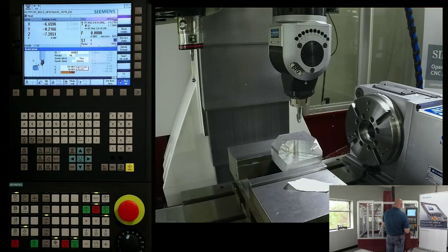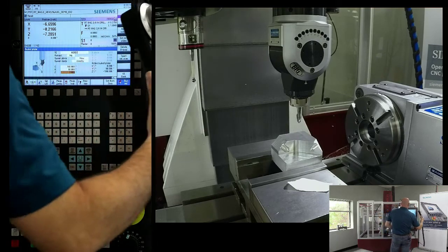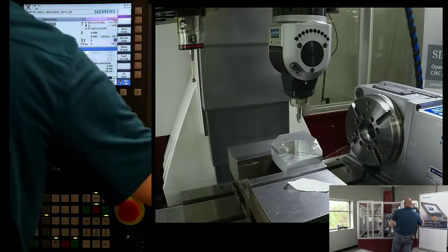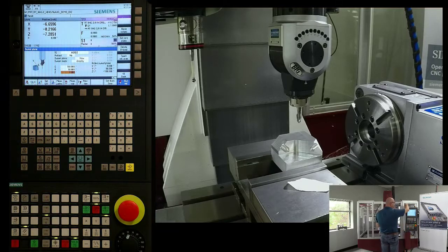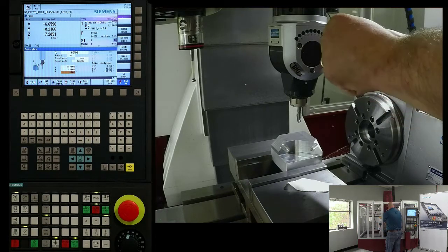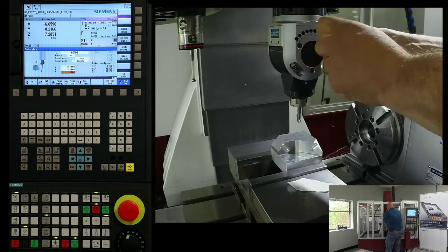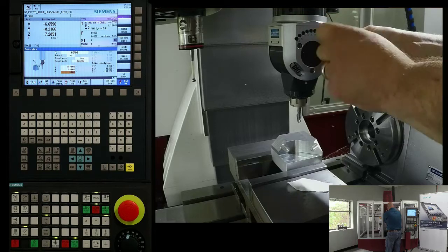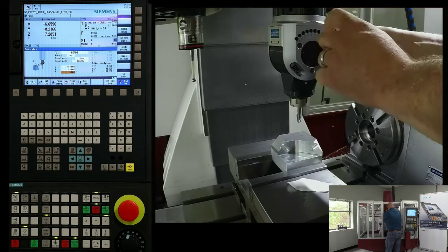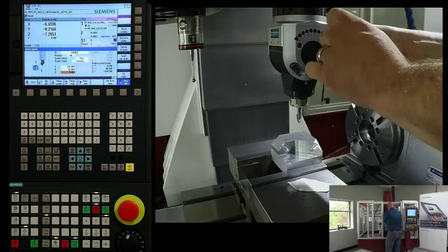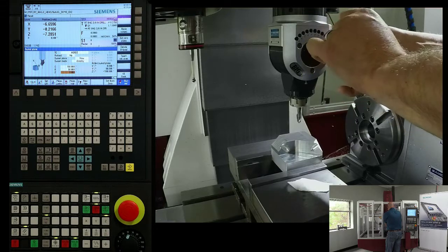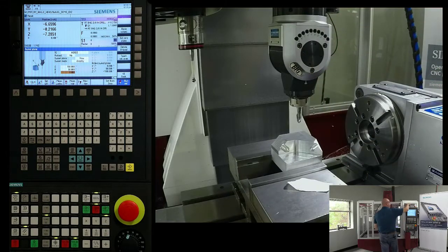Prompts me. Now we do have the ability of telling the machine to go back to a safety retract location. That would be inside the swivel mask. I set this retract to a yes value and I can predefine locations. So there's actually a lot of functionality you can do within the swivel cycle, and it's really quite unique to the Siemens control, how much capability you get and how really kind of easy it is to start to apply.